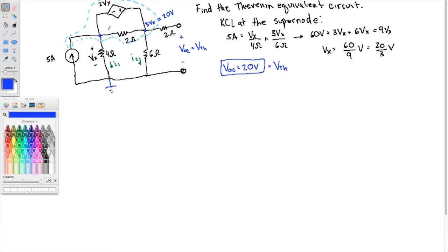Now comes the point where we need to find the Thevenin resistance. Because of the dependent source, we cannot just use the method we've been using. So now we have to change it up to case 2. If you go back to your notes, what you wrote about case 2 says that we're going to connect a short circuit to the terminals, right? And that current there, I'll write it in red so it pops a little bit more, this current ISC, that's the short circuit current, and we need to find it.